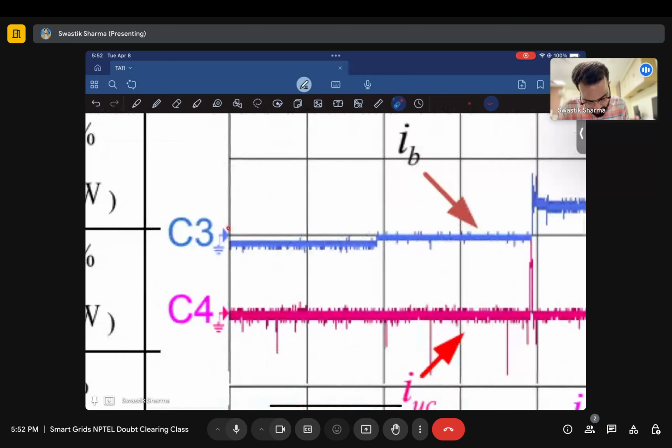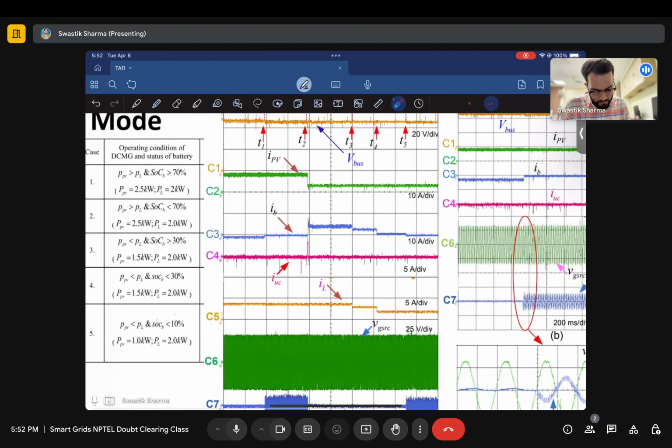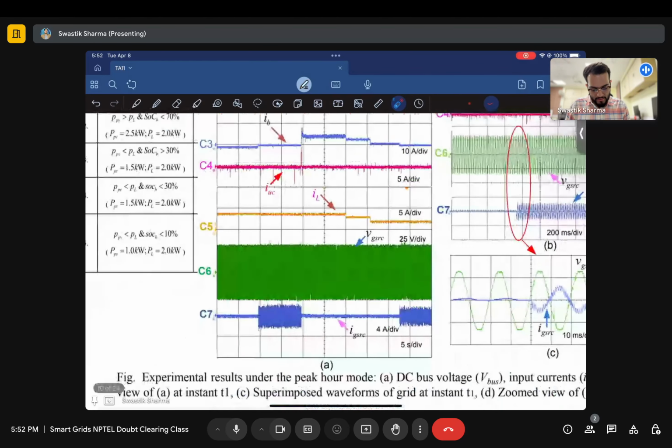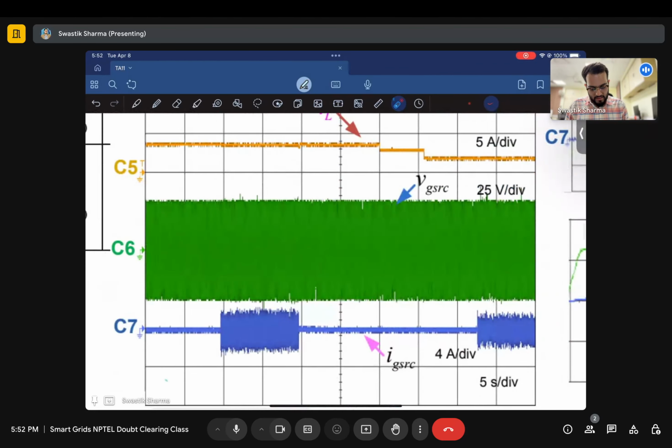You see, it shows this thing. This is grounded. That means that the voltage is at zero. So this is the reference value, right? So battery moves to zero. The transients are still being supplied by the ultra capacitor. The load is still at the same value that it was, but now what you see is there is some current being exchanged with the grid.